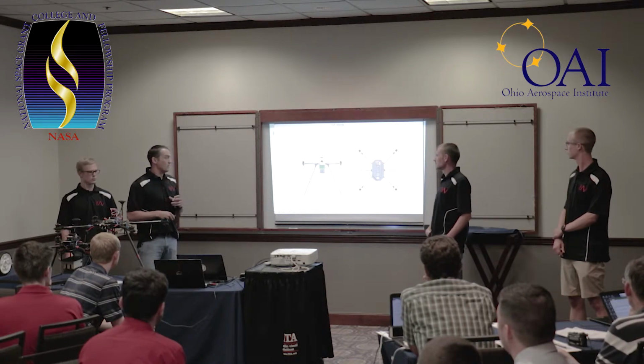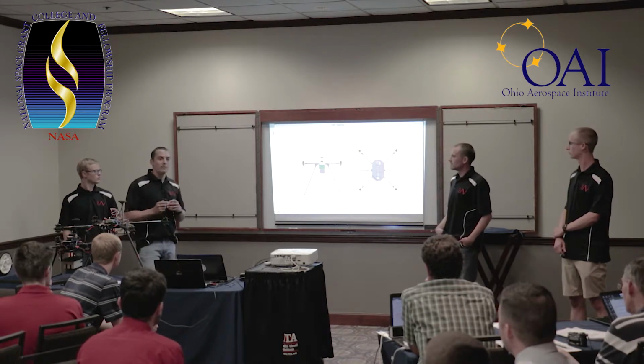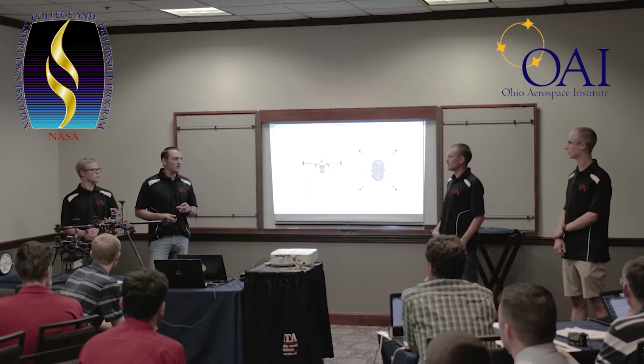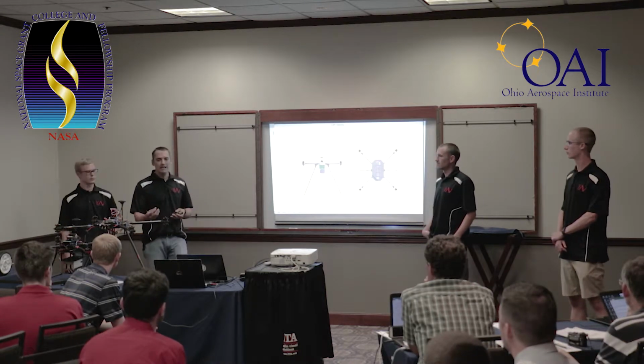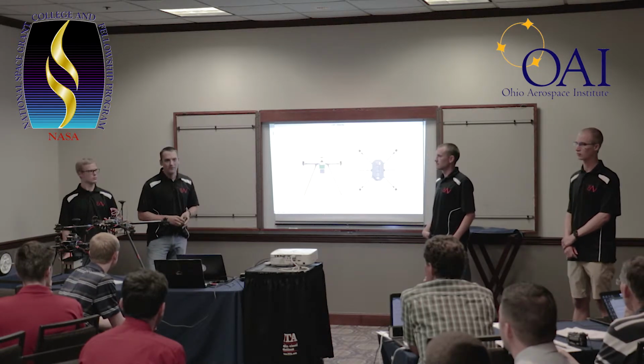So what we did with this platform that we didn't do in previous platforms is we staggered the motors. We put a much more powerful motor up top, something more efficiency-based down low, and that seemed to make a little bit more sense. We weren't eating the weight of the heavier motor down low when we knew we weren't going to be producing the thrust since it was in the downwash region.